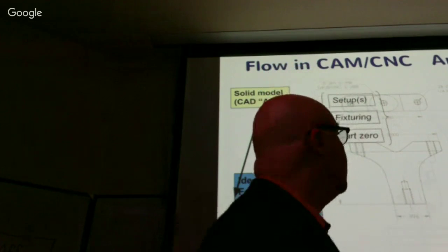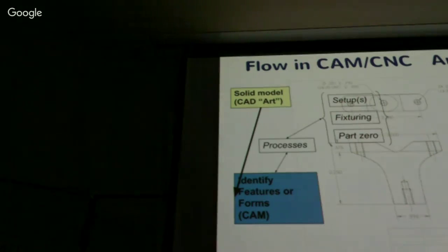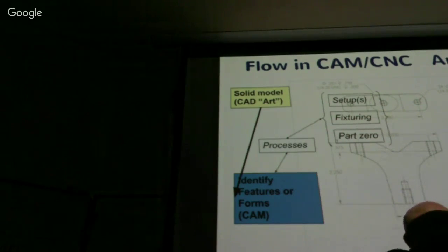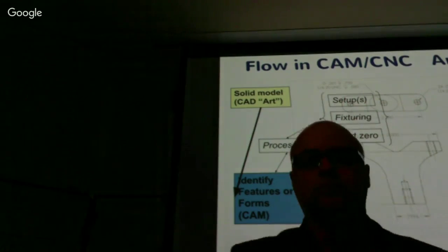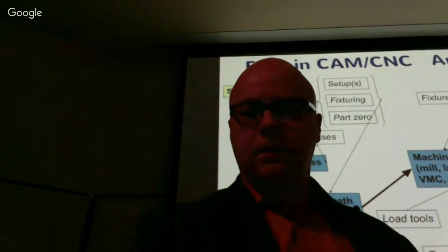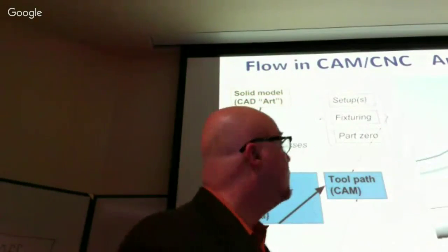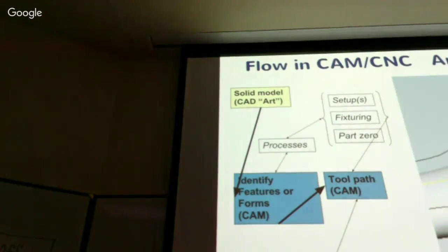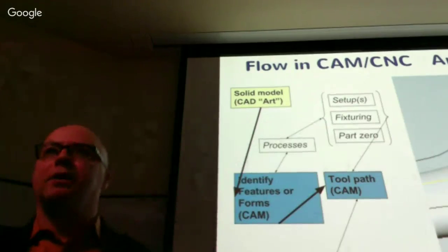First thing we're going to do is put it in the vise. So the stock material is laying down, and the bandsaw cut end is sticking out of the vise. Then with an end mill, we're going to do a pocketing operation to remove the V material, and then a contouring operation that makes it the right length and smooths out all the sharp edges. So that's the first operation.